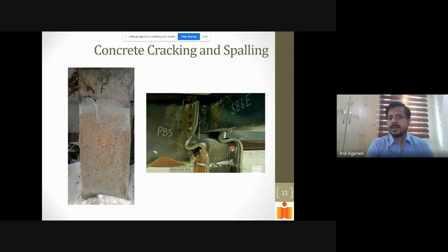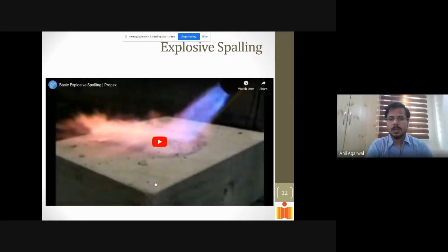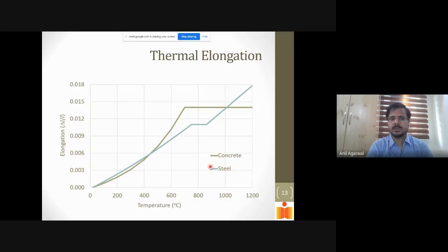Steel, typically after fire, this is a picture from a real building. This was a column that was heated to very high temperatures, and you can see how it has deformed right next to the beam. So these are the 4 beams that are meeting this column at this location, and you can see how the deformed shape of the column looks. So this is a squash kind of failure. Okay. For concrete, there is something called explosive spalling. I'm not going to spend time explaining that.